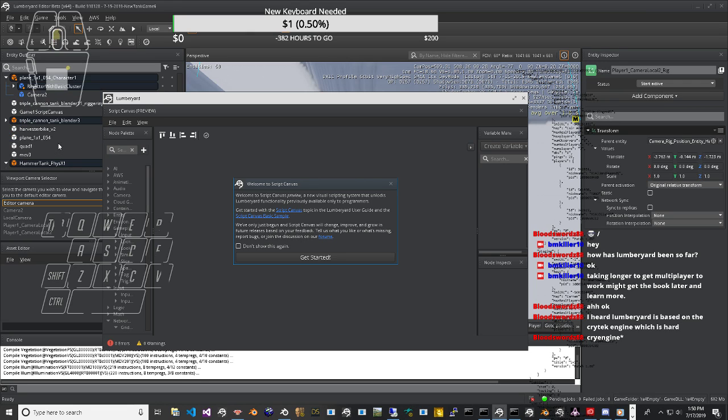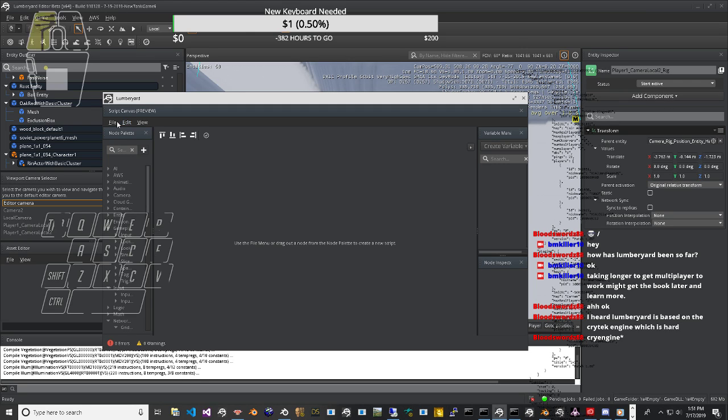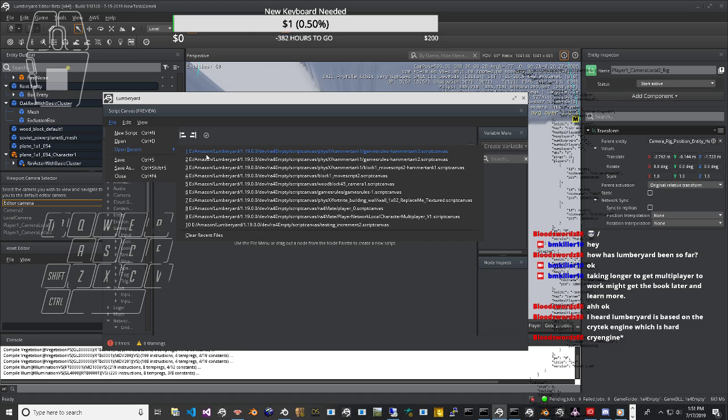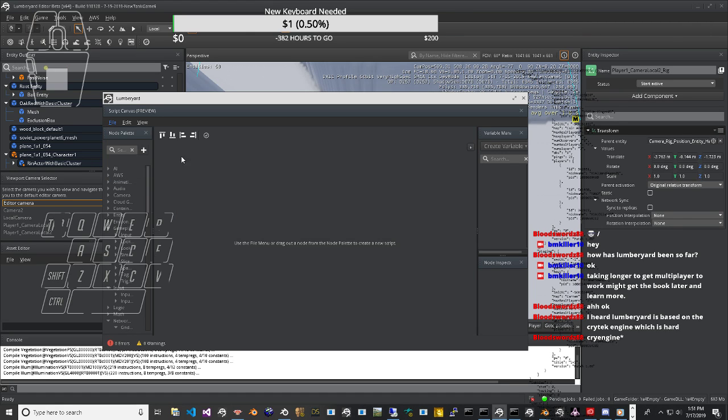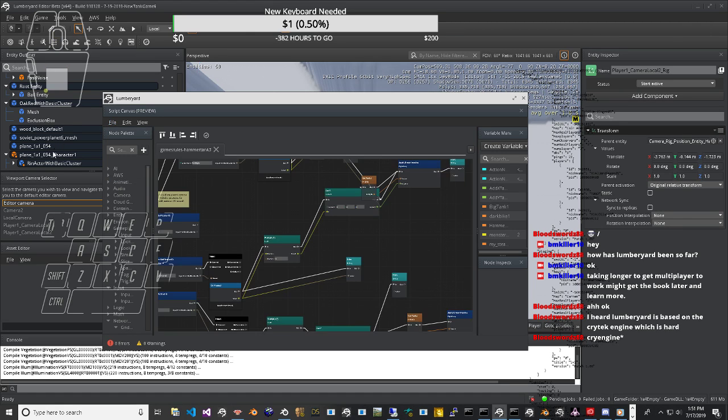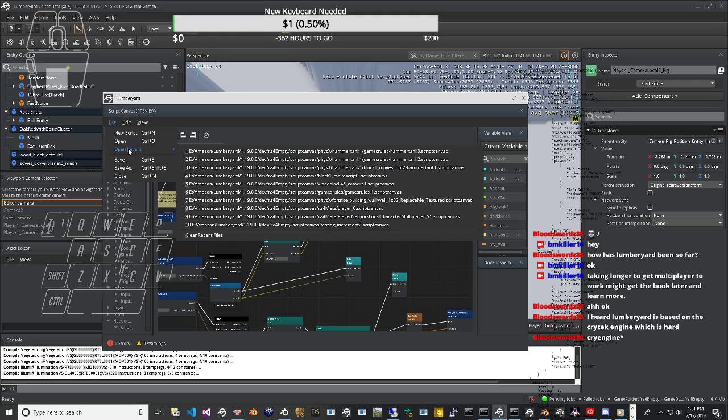Only then can we measure slip angle as the difference between the path heading of the car and the wheel orientation. First is the earth frame, whose axes we write as x, y, z. The z-axis is aligned with Earth's gravitation and points downward. The origin of Earth is fixed with respect to the Earth, and the x and y axes point in arbitrary, but fixed, directions.